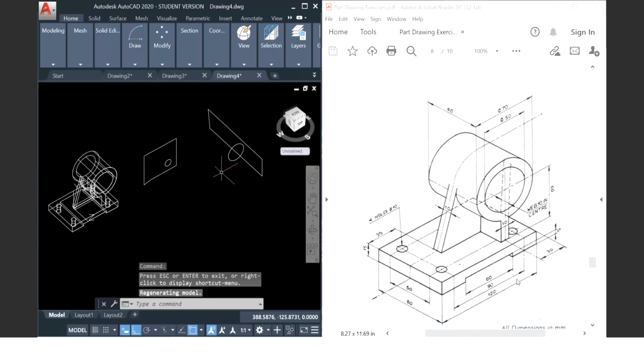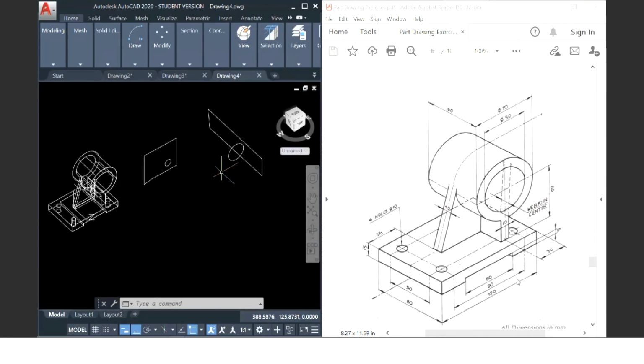Later on when you encounter a problem with this, then make sure. That's why I want you guys to make it a habit. Whatever geometrical drawing or 2D drawing that you want to draw, make sure it's going to be drawn on the XY plane. If that plane is not on the XY plane, change it to become a temporary XY plane.